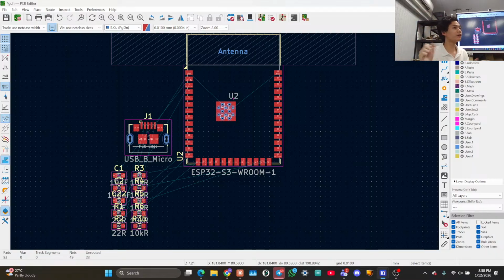Now, a 4 or 6-layer board, which we're not going to touch for now, we'll talk about in lesson 7. But basically, I can have more layers, which means I can have more wires running around. If I have everything in only 1 layer, then wires can never cross over each other. They can never intersect. So only with multiple layers can I do a cross. And there are a lot of things which you can only wire up by crossing wires over. So if you have a lot of components, you just add more layers, and now you can cross over in more ways. You have a lot more flexibility with routing.